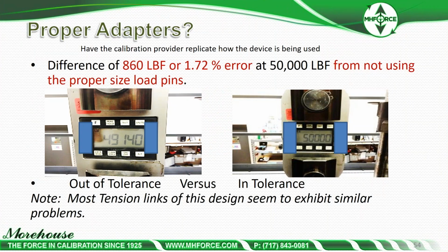Proper adapters. I wish the standard would address fixturing and adapters. It doesn't, so here's what I have to say. Have the calibration provider replicate how the device is being used. If you fail to do this and you do everything else right, you will still be behind. Here's a situation. Customer sends in a device, please calibrate it. They do not send the pins, the forged pins that are being used with the instrument.